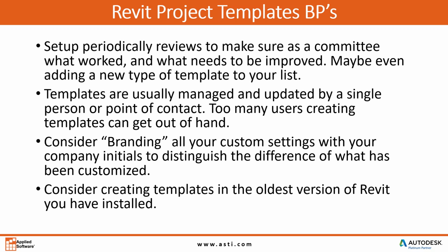Consider branding all of your settings. So if you customize it in Revit, and this is going through the checklist, right? So if you go to your text styles, 1/4 inch, 3/32, 1/8, headers, titles, all your text styles and dimension styles, they should have your company initials in front of it. It should say ASTI or my company, ABC, whatever. You should brand it with your initials so that that is your custom standard. And any greenhorn or new user that's coming into your office that just got hired can look and see everything that has your company initial is kind of obvious that that's what you use as your company standard.